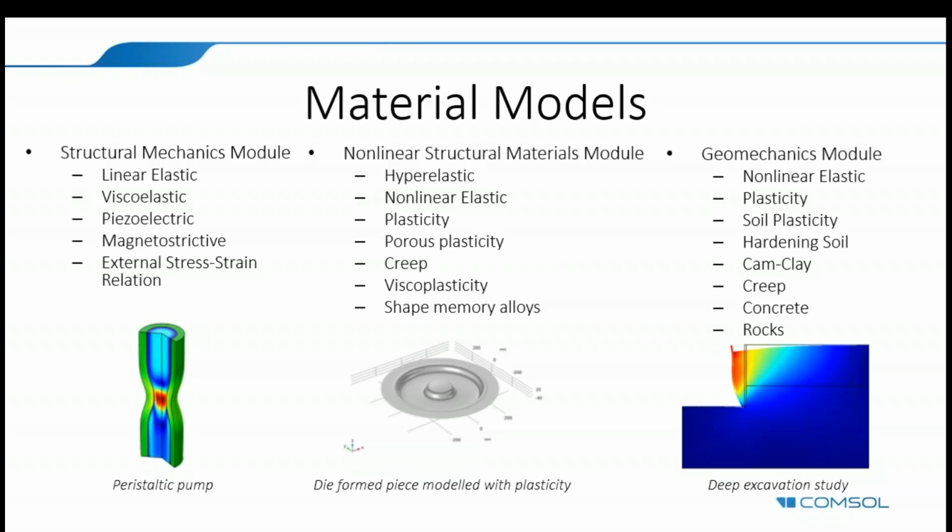We also have strain rate dependent viscoplastic material effects that can be modeled using either viscoplastic or creep material models. This is an effect that's usually driven by heating or can be driven by a combination of thermal and mechanical loading. It can be characterized as a solid behaving somewhat like a highly viscous fluid, where the solid material actually flows or creeps.